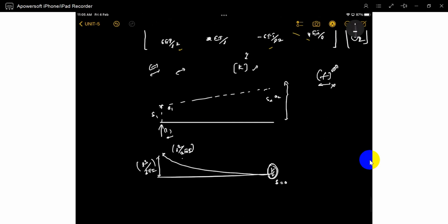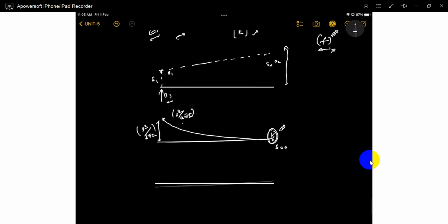You will get it like this. Otherwise, like this also you will get it. If you apply a unit rotation, or a unit force, you will see how it differs. If you restrict those, in reality you have to allow those also. If you apply a unit force, a unit moment, what is it? 4 by L, you will get L by 4, that is the rotation you will get here. Here also L by 2, sorry.